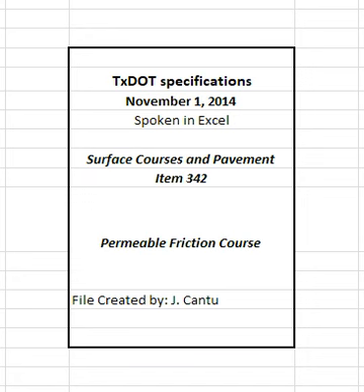At any time during production, the engineer may require the contractor to verify the following based on quantities used. Lime content, within plus or minus 0.1% of JMF, when PG binder is specified. Fiber content, within plus or minus 0.03% of JMF, when PG binder is specified, and CRM content, within plus or minus 1.5% of JMF, when AR binder is specified.